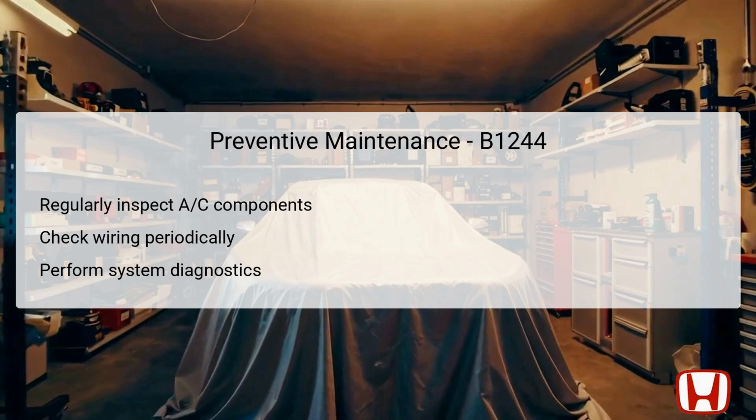This should include checking for loose connections and ensuring that all electrical connectors are secure and free of corrosion or damage. Performing periodic system diagnostics can help catch problems before they escalate. So using tools like the Honda Diagnostic System, HDS, is advisable. Keeping proper coolant levels and ensuring no blockages exist within the HVAC system will further enhance the longevity and performance of your vehicle's air conditioning. Proactive maintenance significantly contributes to the reliability of the vehicle's climate control, ensuring a comfortable ride year-round.